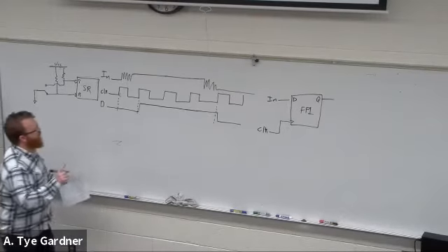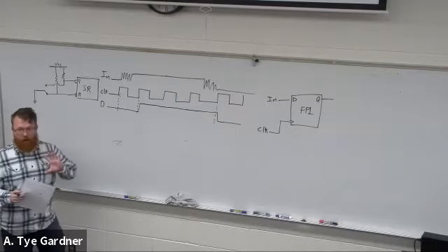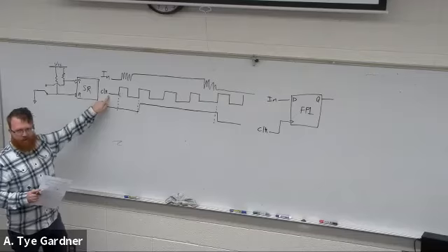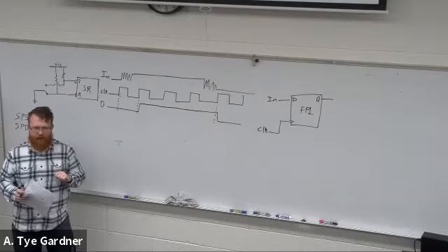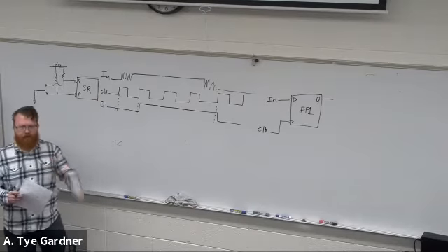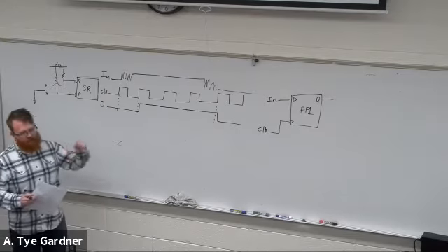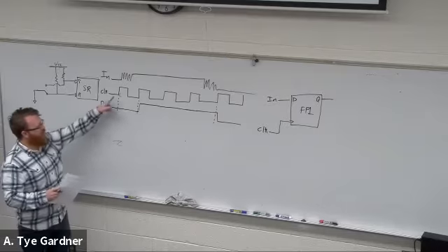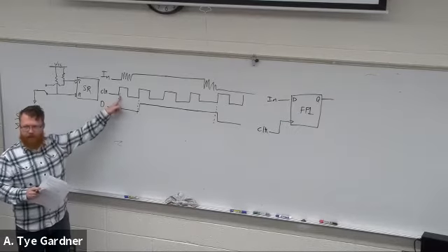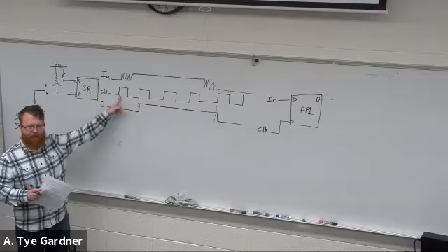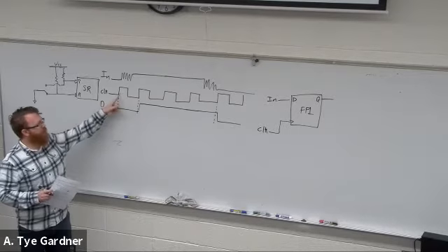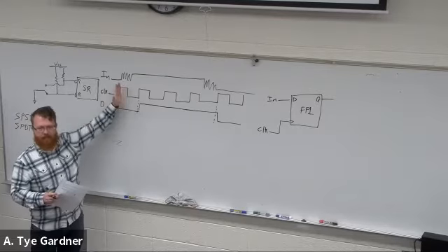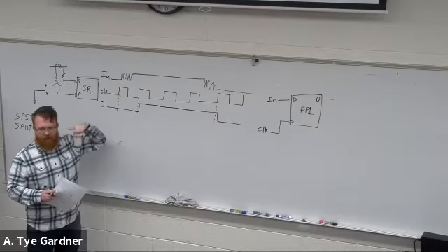Oh, one thing that I need to say is that for this one to work at all, you need your clock period to be long compared to the amount of time that you have a bounce. So we have to create a fairly large clock divider, able to make a small clock to make this happen. Because 400 megahertz is still very fast in mechanical bounce terms. So if I were to try and do this with a 400 megahertz clock, there's no way it looks like this. There's going to be like 100 and something clocks in this region potentially. So you're going to be all over the place.